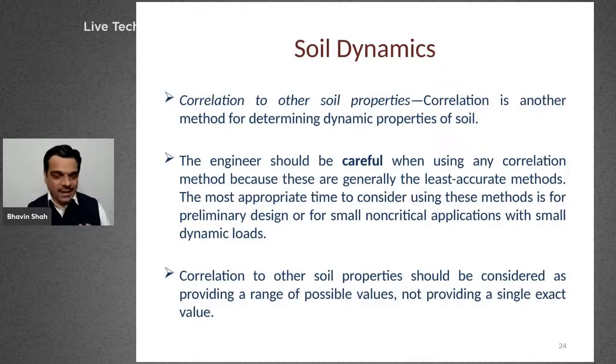Now I always put the statement that the engineer should be careful when using any correlation method for this kind of foundation we are discussing, because these correlation methods are generally the least accurate methods, and the most appropriate time to use this least accurate method is only for the purpose of preliminary sizing.